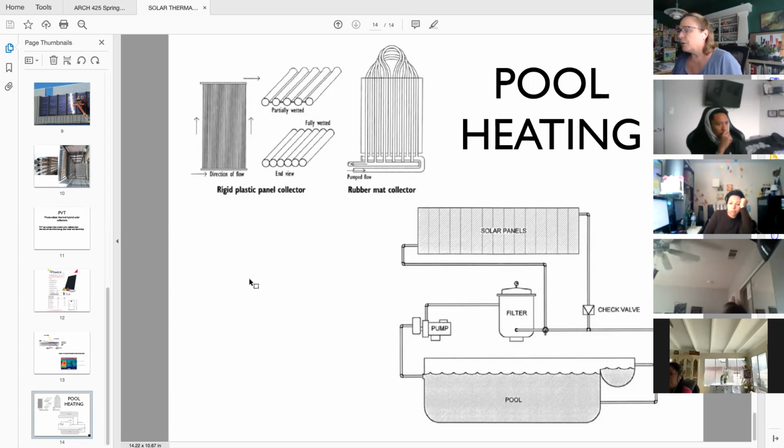Versus a pool collector, let's say it's 12 pounds for 4x8, and there's probably a gallon of water in it. So 12 pounds for the collector plus 8 for the water, say 20 pounds overall over 32 square feet, instead of 640 pounds. My point being, a lot less weight, a lot easier to support.